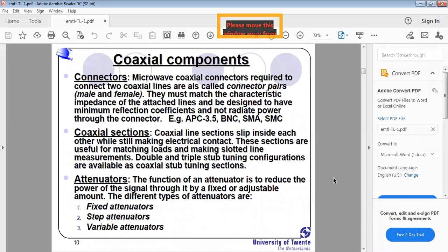When the resistance value decreases, the current flowing through the wire increases, and whenever the current increases, the fan speed increases. From step one to step two, step two to step three, step three to step four, the fan speed increases. This is possible by decreasing the resistance for each step.